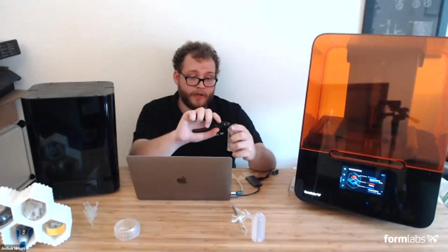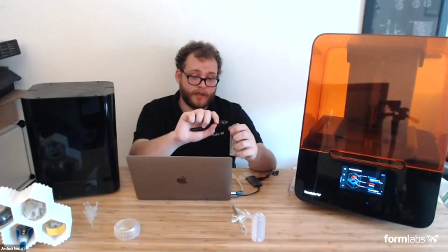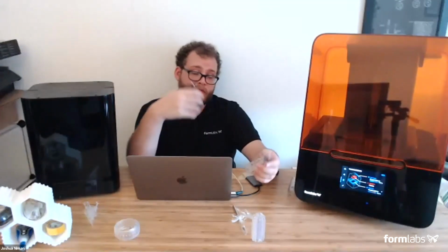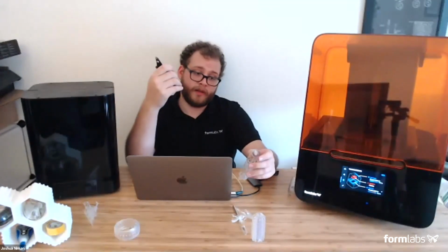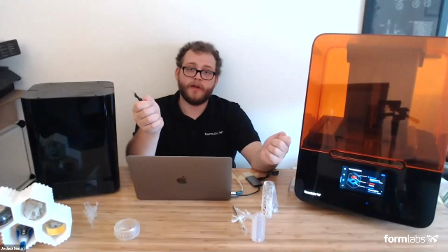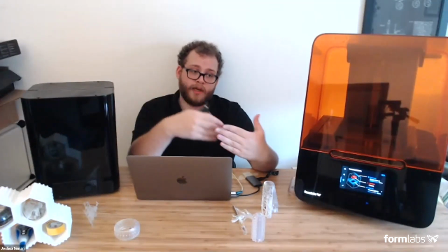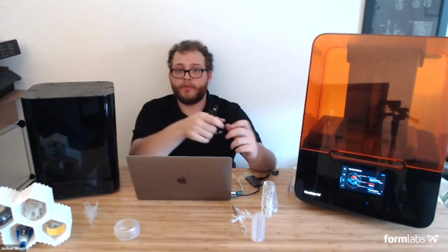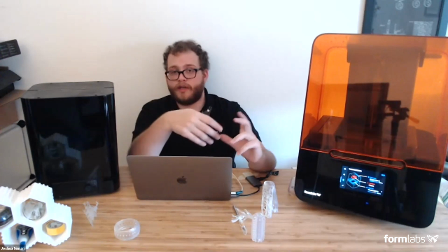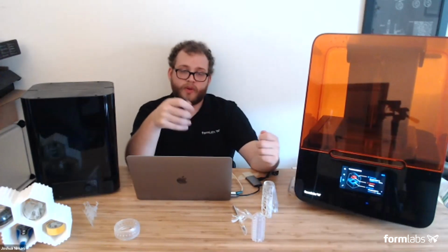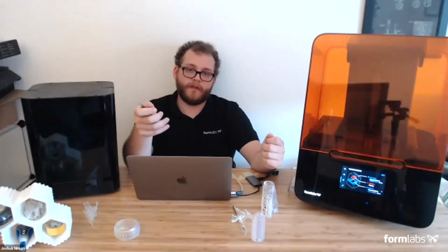That makes life a lot easier when you're working with things like this, because one of the big concerns that we've sort of overcome, but not fully, with soft materials is when you yank one of those supports off, is it going to pull away cleanly at the surface of the material? Is it going to pull away part of the part itself? Or is it going to break somewhere along the stock? And in the case where it pulls away part of the part itself, it's really hard to fill those craters.